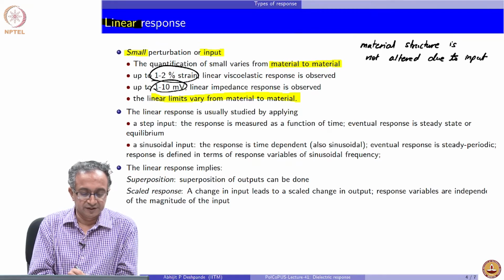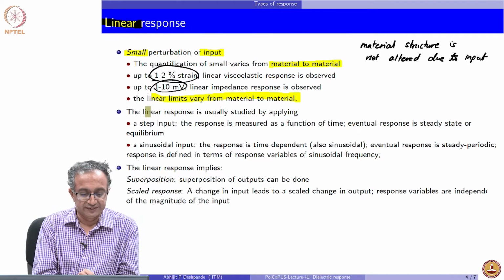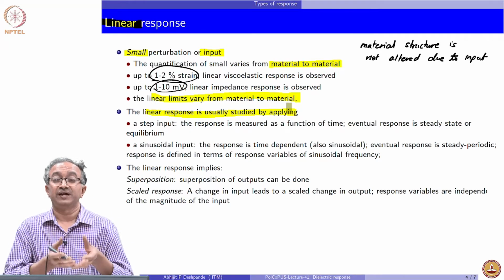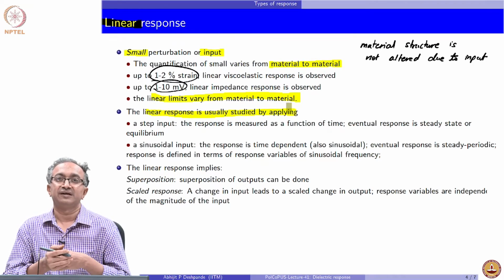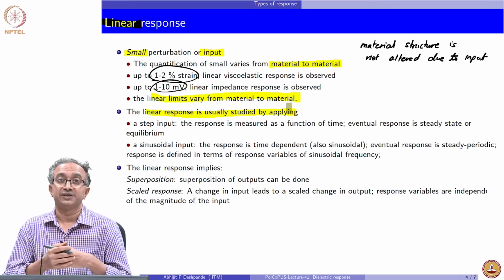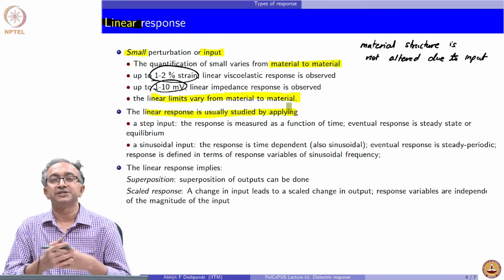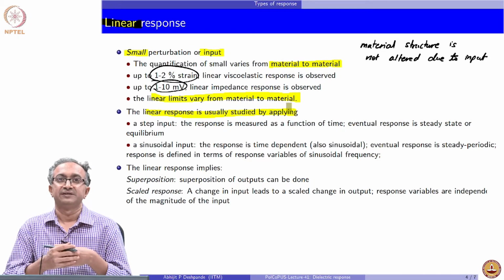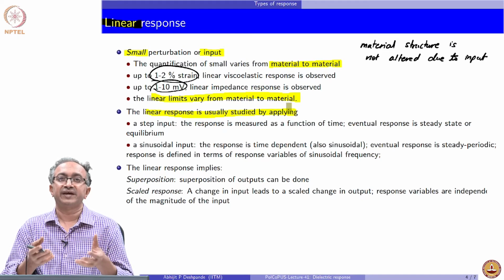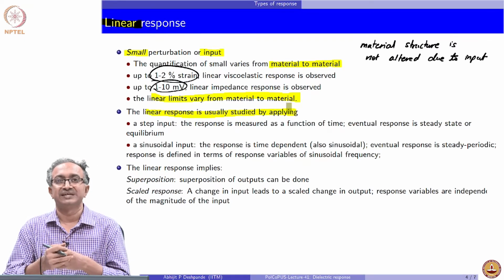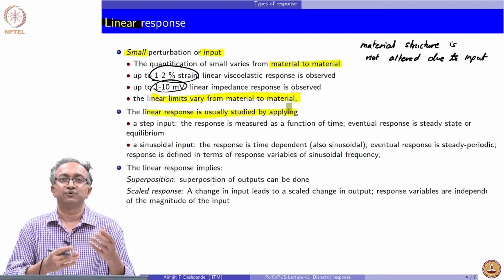So, linear response can be studied by a variety of ways, and this is now different compared to when we had looked at, let us say, static testing of mechanical response. There we never brought time into our discussion. Even when we define viscosity for a fluid-like medium, we just say stress is proportional to strain rate. So, whatever is the instant of time, it does not matter. If I know the strain rate, I know the stress, or conversely if I know the stress, I know the strain rate. Even in the case of solids, if I know the stress, I know the strain.